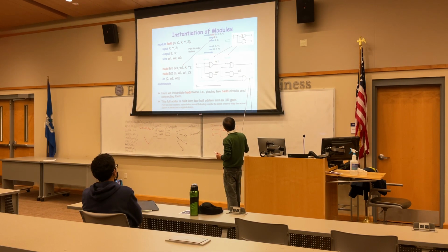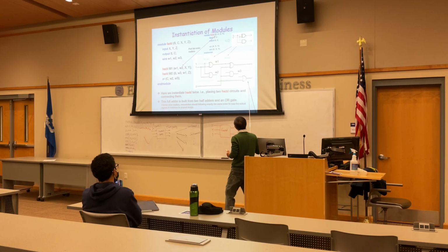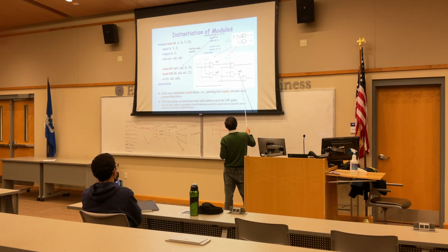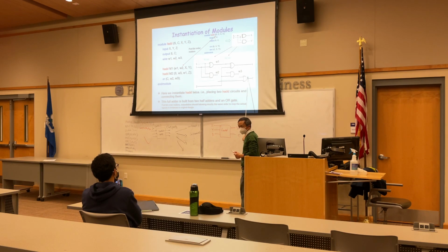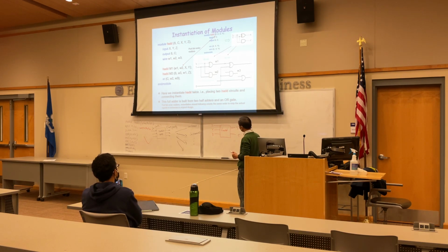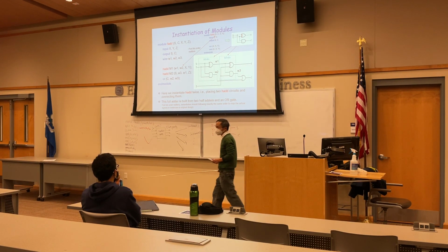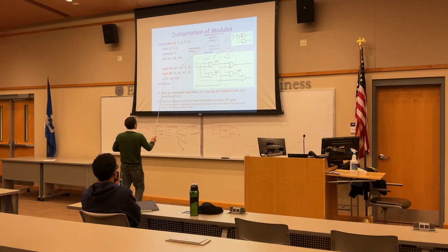How does it carry out? The first two inputs together give a carry out, and then this other half adder gives another carry out. You have the actual carry out either from here or from here, and that's going to be the final carry out. Okay, we're going to use half adders. Now for this circuit, how should we use the structural model to design with instantiation?